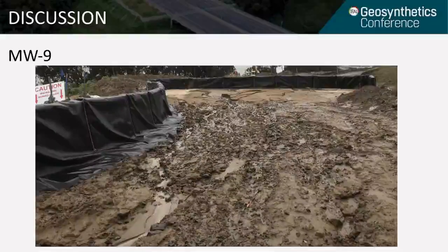While basin MW9 was placed on a slope with an approximately 10% grade, contained empty barrier walls, and also utilized corner walls, it didn't experience any stability issues. And it appears the compacted soil that it was placed on top of was likely the reason for its increased stability. This is because the coefficient of friction between the barrier wall pieces and the soil is generally higher than that of the barrier wall and asphalt. In addition, the barrier walls were able to settle into the soil as opposed to sitting directly on top of relatively rigid asphalt.